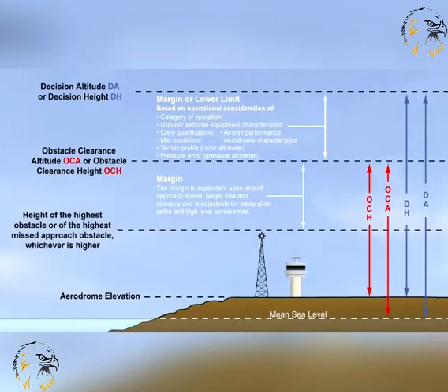The decision altitude or height, DA or H, for a precision approach procedure is the lowest altitude or height above the elevation of the runway threshold, at which a missed approach must be initiated when the required references to complete the landing visually cannot be seen. Going around at this juncture will ensure compliance with the obstacle clearance criteria of OCA or H. The various factors which dictate that the DA or H equals or most often exceeds OCA or H are shown